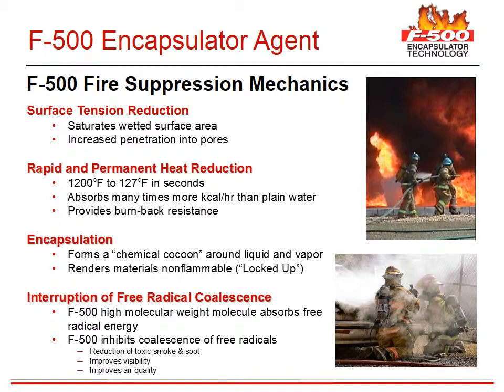F500 encapsulator agent instantly draws the heat from the fuel and surrounding structure, eliminating burnback. The micelles are formed around the liquid fuel and vapors, rendering them non-flammable. And finally, F500 absorbs the free radical energy, reducing toxic smoke and soot, resulting in better visibility and air quality.